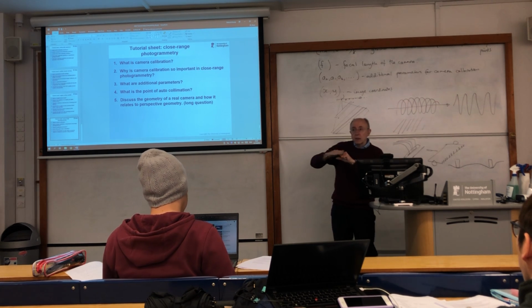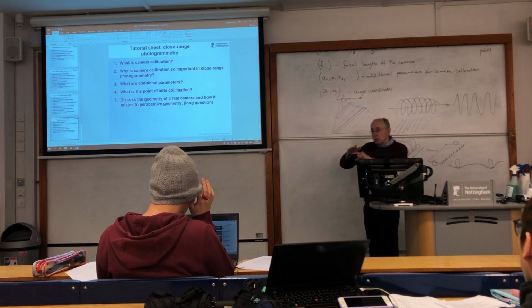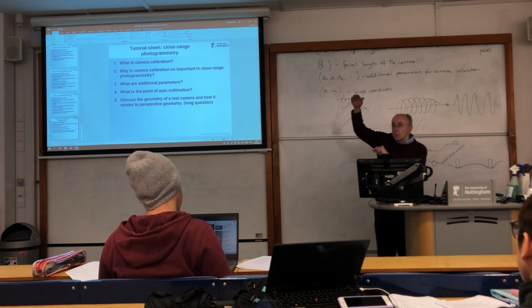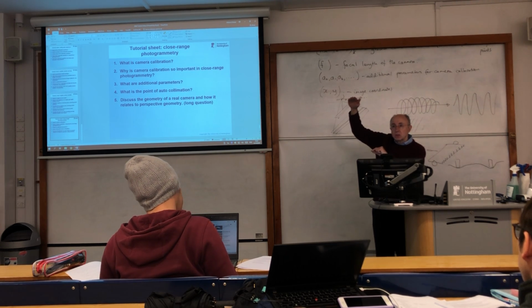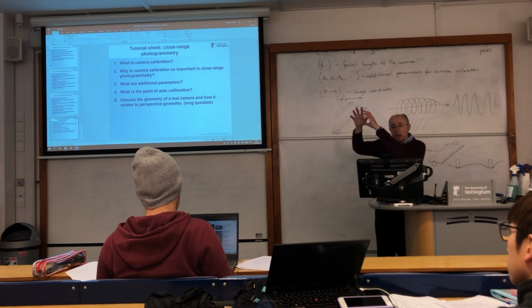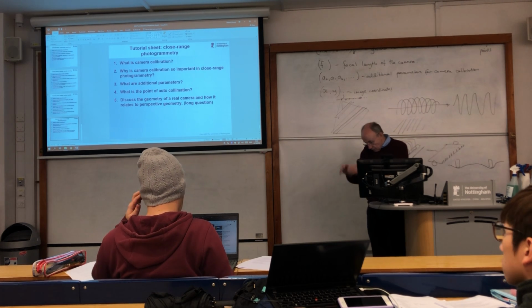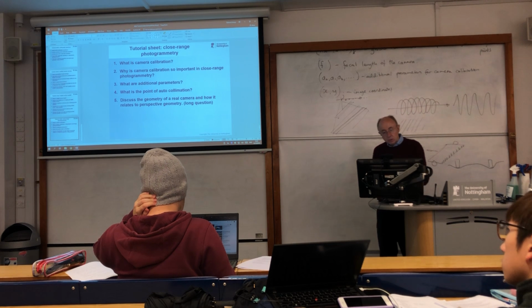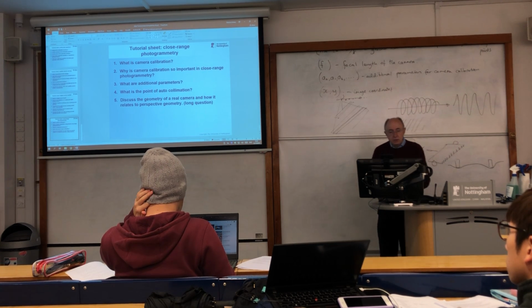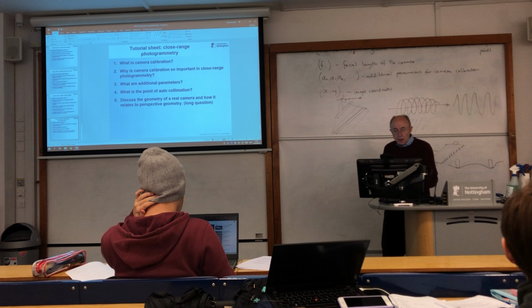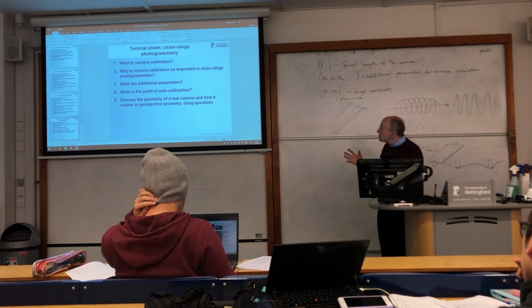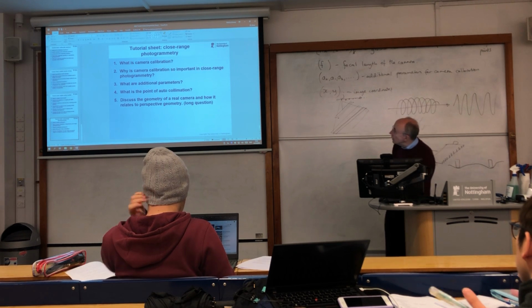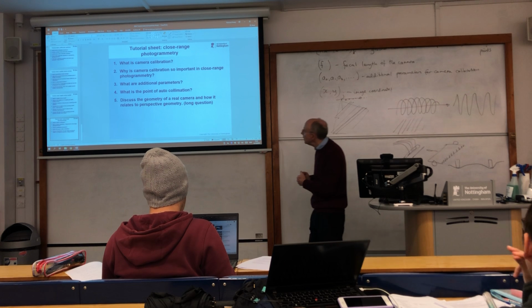And you can start then getting problems with fitting on your ground control, because the aircraft and the internal geometry of the camera is actually pushing the errors down onto the stereo model, or in effect the ground surface. So that's really number two, and I've expanded that to talk about the airborne case a little bit.